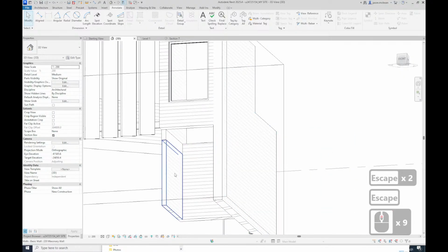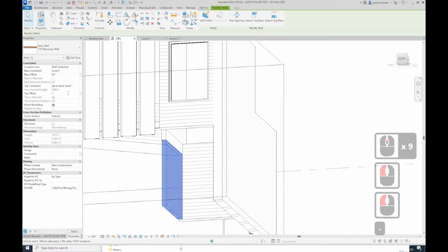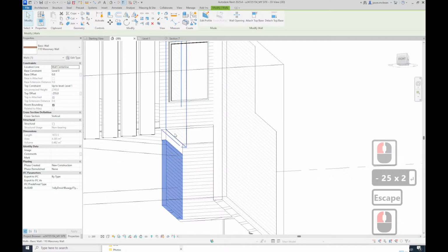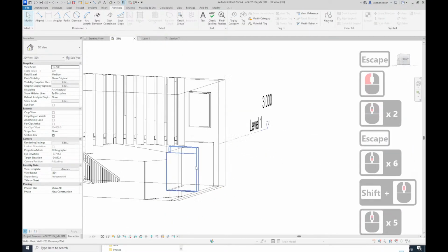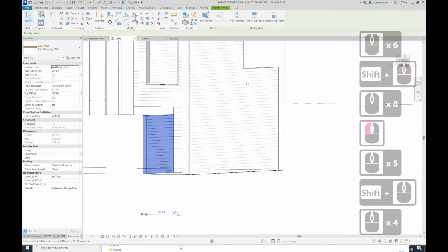Okay. All the walls that are on this level must always stop underneath the slab, so minus 255, so they don't go into the slab. Okay, see it there. Wait, what do you mean? So basically, okay, that's been joined, so we'll detach that.